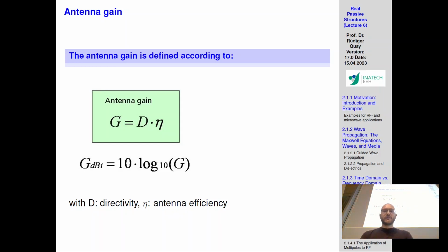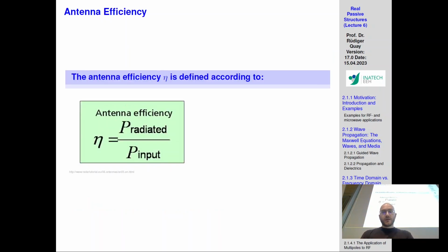Obviously, horn antennas have a higher efficiency. Antenna efficiency is the radiated power over the input power. The input power is the power that gets driven by the amplifier, by the power device. We have also mentioned that we see power devices as two-port structures. So they have input and output waves: waves that are incident to the input, waves that go outwards from the input, waves that are incident at the output, and waves that go outwards. They can be voltage waves. These voltage waves, when squared, will give you the power waves, and with the power waves you can define the S-parameters and so forth.